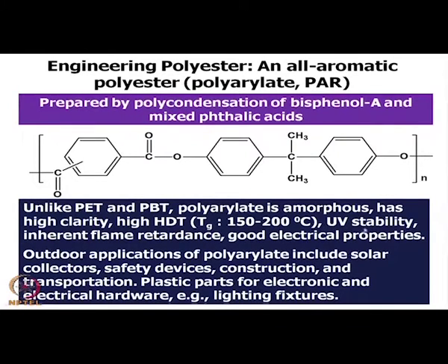This polymer is stable to UV radiation and provides inherent resistance to flame, that means it is a fire retardant polymer, and shows very good electrical properties. Since there are no ionic groups present here, electrical properties of this polymer are good, but an oxygen atom is there, so it cannot be fully resistant to a high voltage electric field, but at low voltage this polymer shows good electrical resistance.